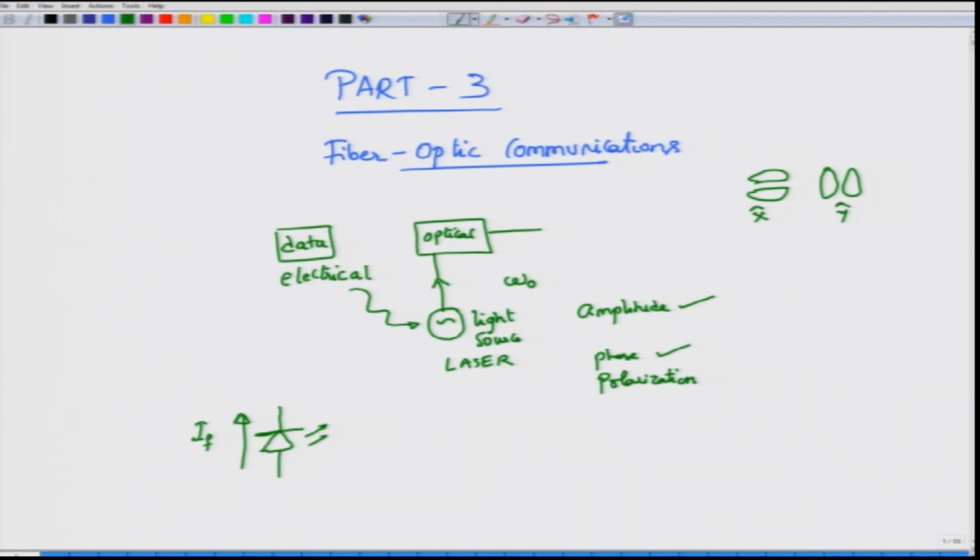We know that when we forward bias the junction, you are going to move a lot of electrons from the valence band into the conduction band, and because you have used heterostructure lasers, you would confine these carriers in their appropriate bands, whether in the conduction band or in the valence band. Just a small amount of forward bias current would then induce these carriers to recombine and give off radiation, which, when you enclose it with mirrors, would form a self-sustaining emission of light called a laser.